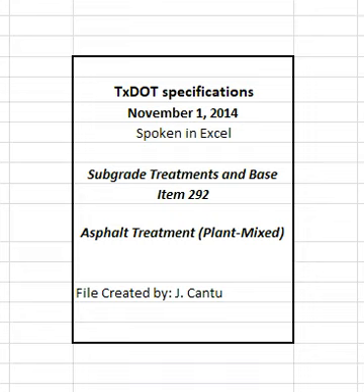If in-place density is between 0.1% and 1% below minimum density, investigate the causes and make the necessary corrections. If minimum density is not obtained within 1 full day of operation, cease production. Resume production after placing a test section of 1 lane width and a maximum 0.2 miles long that demonstrates that minimum density can be obtained. Repeat this procedure until producing a test section that meets minimum density requirements. Place no more than 2 test sections per day. Increasing the asphalt content of the mixture to increase in-place density is allowed by approval only.